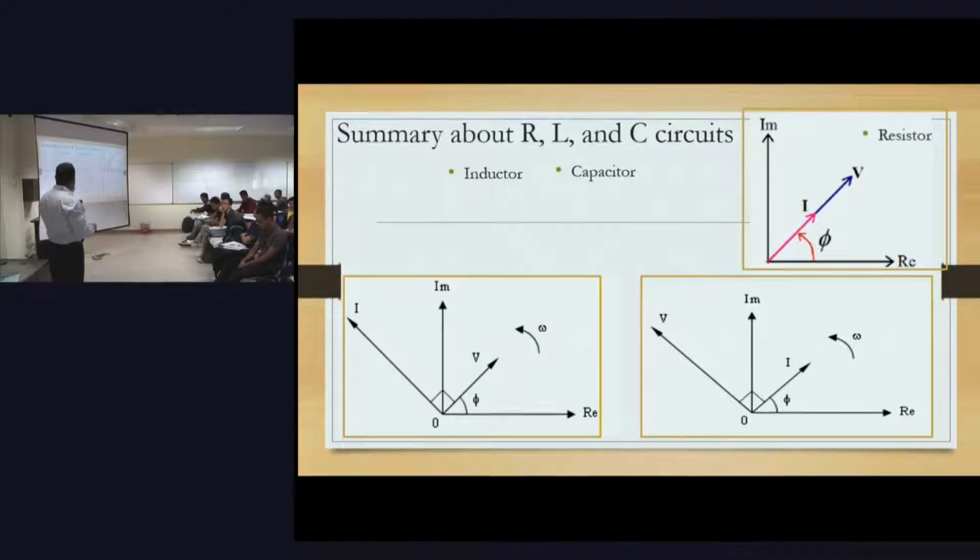Anyway, so this is the resistor. It's very easy. We understand this now. What about the inductor? Oh, sorry, that is the inductor. So this is the current. We started with current. It doesn't matter. So basically what you need to know is, in case of inductor, the voltage leads the current through it. So if this is the current, the voltage is leading the current by 90 degrees.